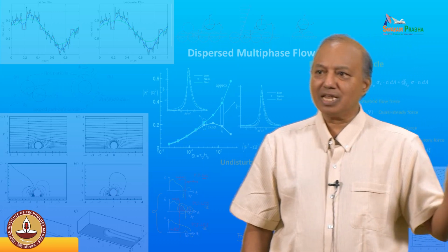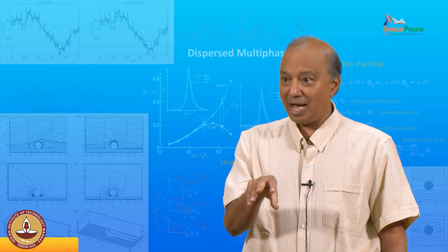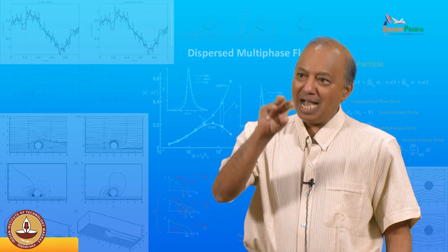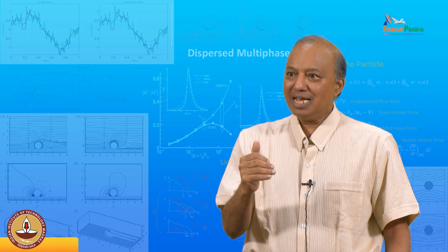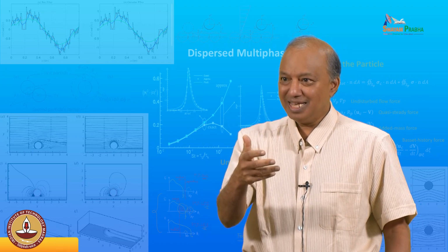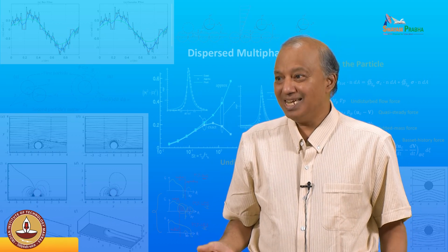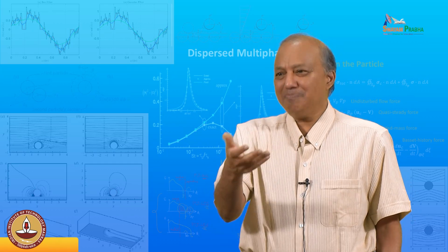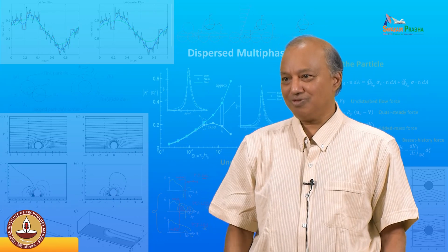You remember in the previous lecture I was talking about when mass loading starts locally. Mass loading means the mass of particles that are in there divided by the mass of the fluid. If that ratio is even 0.1 or 0.01, then the particles, just by their presence there, make the fluid heavy. Therefore, you have to do some two-way coupling.